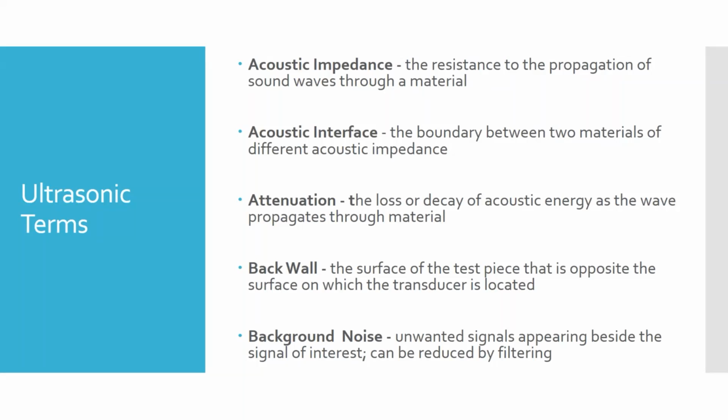So just understand that kind of stuff: vibrations that travel through your tabletop or other things can potentially have an impact or show up as a received signal. It's a microphone. A microphone doesn't care. Now there are filters in there. The testers are designed to help filter that out, but you can still get an effect if you're testing in the 100 kilohertz range and there's 100,000 hertz sound traveling through a piece of material. You wouldn't be able to hear it. It's outside of the range of hearing, but that little piezoelectric sensor inside of here would be able to hear it.